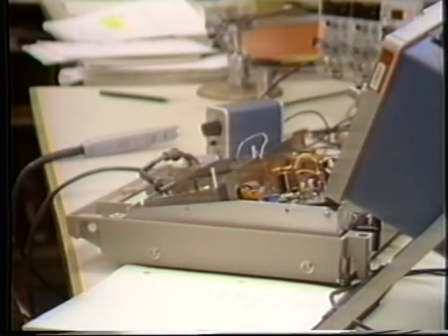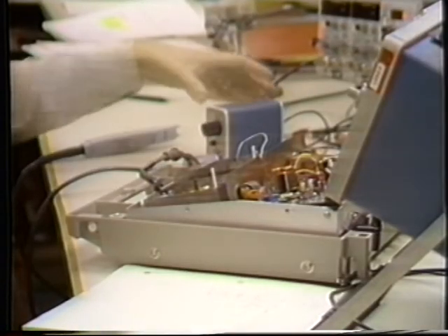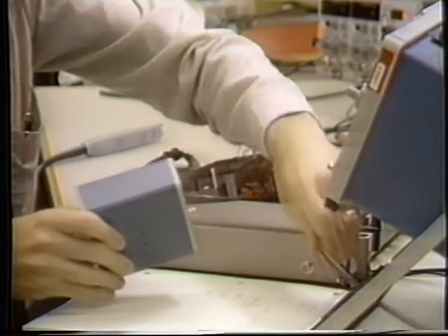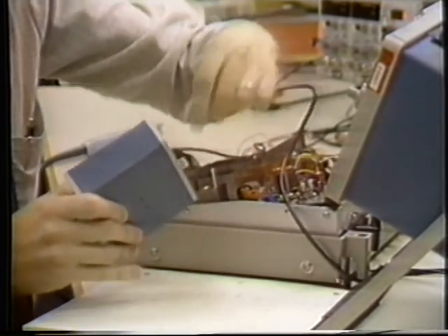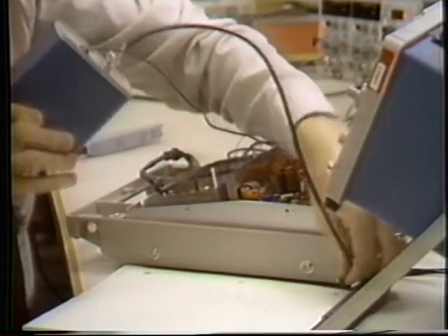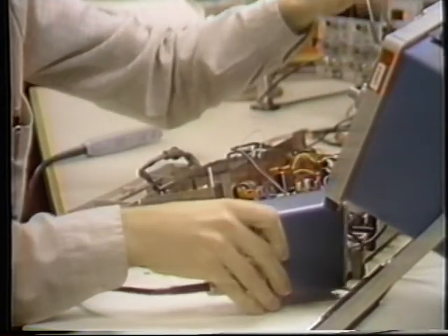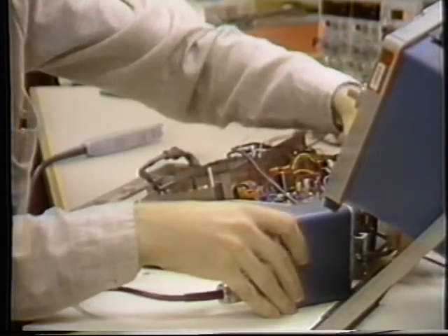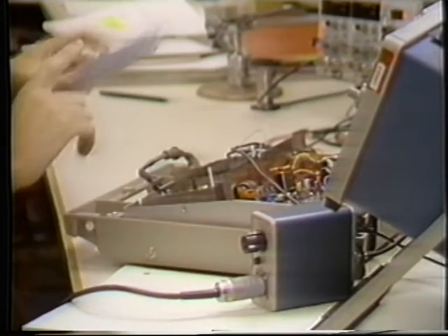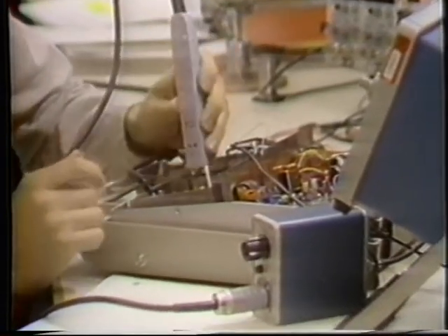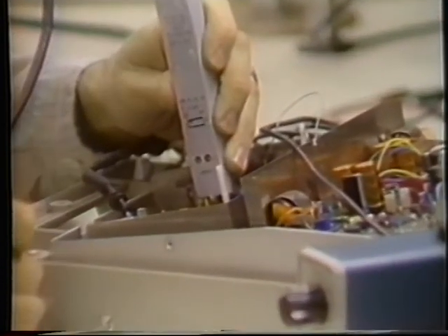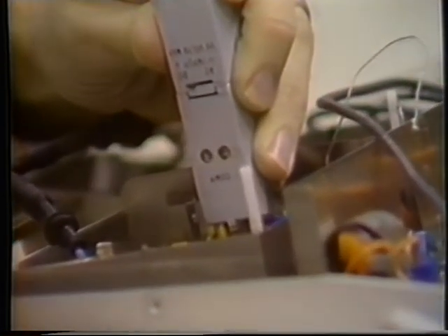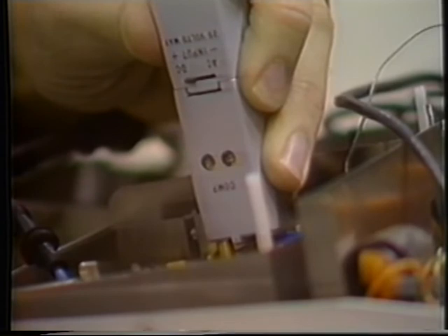All the measurements we've made so far have been with respect to ground or single-ended. Often we need to measure the voltage across a circuit element neither of whose ends are at ground. Or we may need to observe a difference signal under the presence of masking common mode signals, such as hum or induced EMI. You could use 2 matched probes and a differential plug-in, or try a 2-channel oscilloscope in its A-B mode. But the best way to do this is with a different kind of active probe.